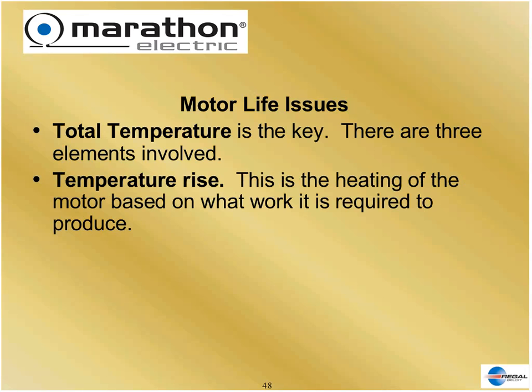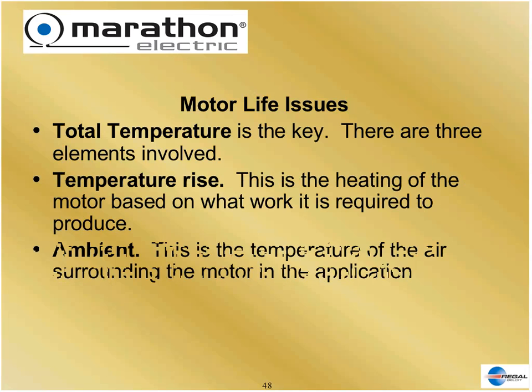That's what temperature rise is. The second thing we talk about is the ambient temperature. That's the surrounding medium, usually air, it could be water, that surrounds the motor in the application. That ambient temperature is part of the application. It's not part of the motor design. It has nothing to do with the motor design yet.